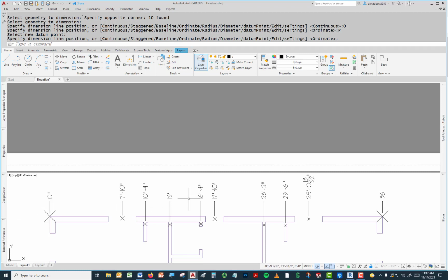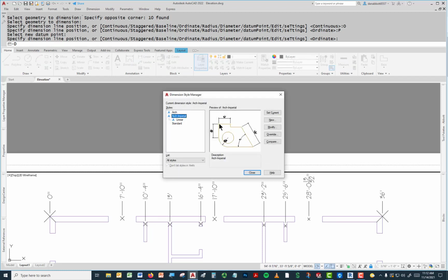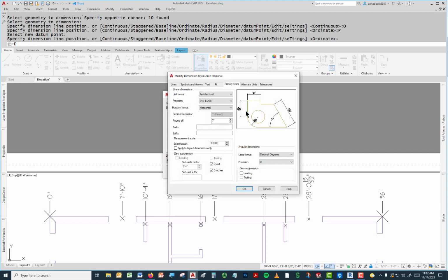So I can put a tape measure down, roll it out, and just make the marks any place I want to go. And again, the whole thing here is just to be able to find errors in where I put my geometry. Under the dimension style to do that, it's right under here under primary units, 1/256.